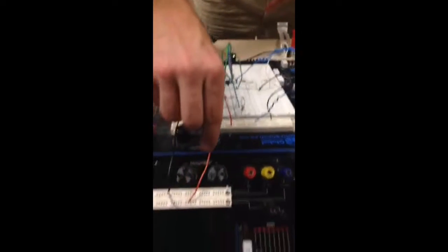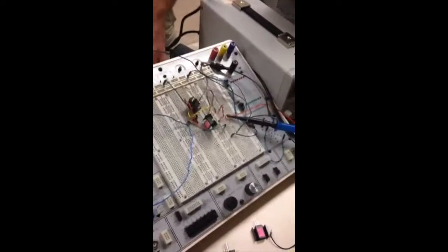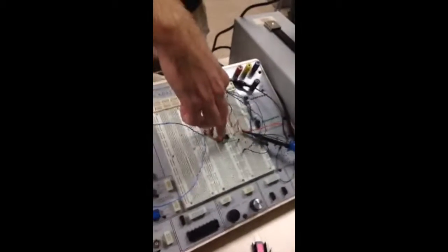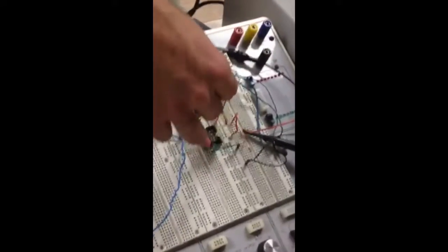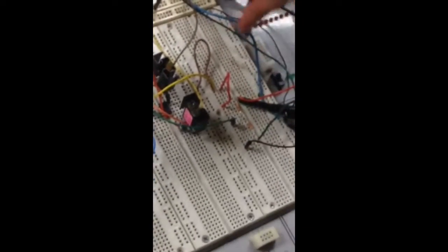We have negative 5 volts for the op amp and positive 5 for the VCC and VEE, and it comes over to the push-pull amplifier, which will be about a 2.2 volt input for the push-pull because of the gain of 2. And these are powered with 10 volts and negative 10 volts for the push-pull, which connects to the voltage divider with the 8 ohm speaker, which we can turn on right now, and we'll explain the output voltage with different frequencies.